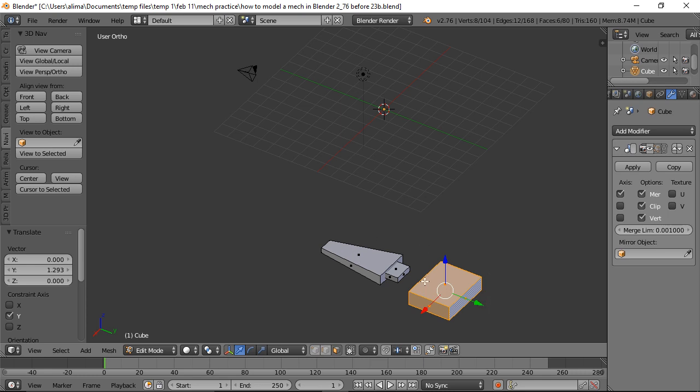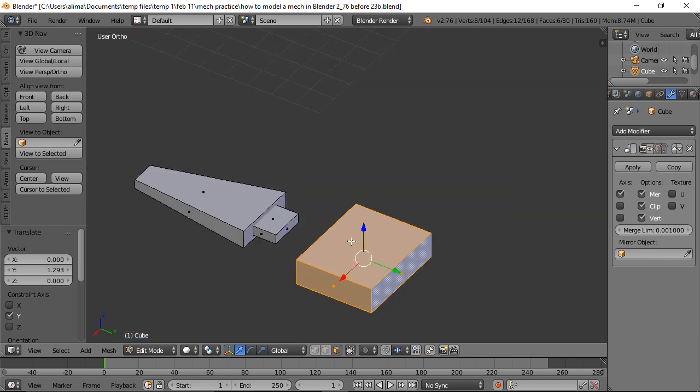Right now, we're looking at this geometry. We have all this space on our screen. So what we're going to do is press Shift, and while holding Shift, press B. We're going to draw a box around this geometry, and all that does, when you press Shift B, is allow you to zoom in to where you drew the box, which is very cool. I learned that from Darren Lau a little while ago, and really like that zoom in technique.